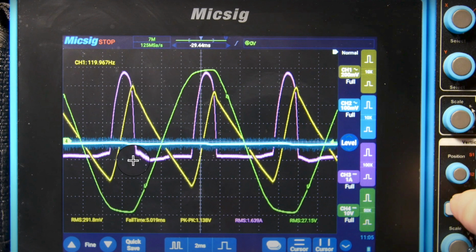One cycle, we could say, is where this AC waveform crosses 0 right here, comes up, down, and then crosses 0 going in the upward direction like it did over here. So that's a cycle from here to here, okay? But you notice there's 2 purple waveforms in that cycle because of the positive pulse goes up and then the negative. See the negative waveforms down here, but the bridge rectifier is going to flip that over so it's going to be on top, right?